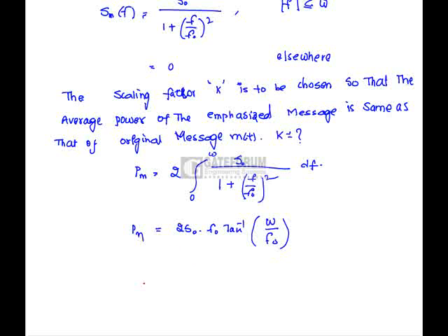Here the power of the emphasized signal is as follows. Suppose this is the pre-emphasis filter, with input PSD S_M of f. The output PSD is the filter response H_PE of f whole square into S_M of f.